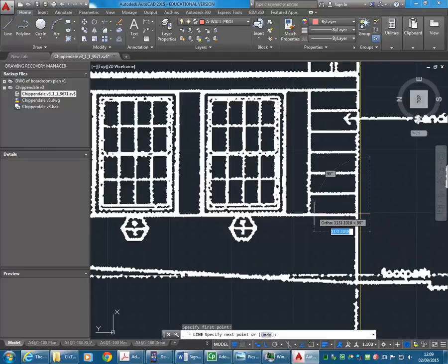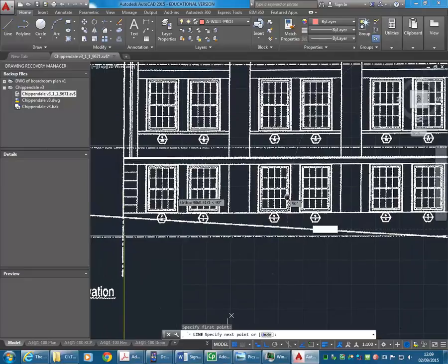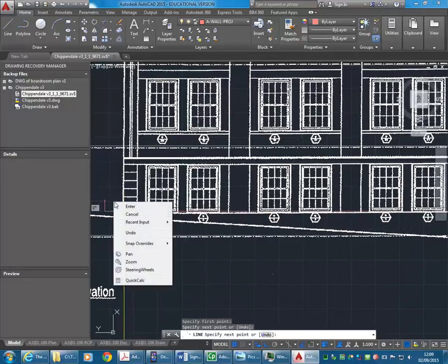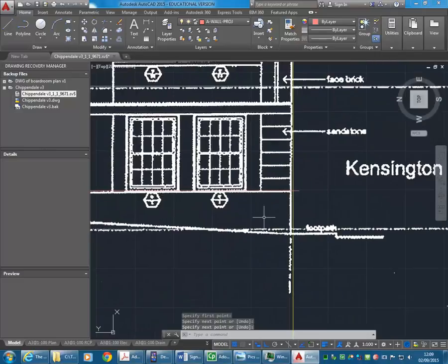Oh, there is. But it won't pick up the lines. Not these, no, and especially because they've been scanned in, it won't even snap to them. No, look, it's actually a bit of a secret in Revit that it can trace over pixel-based images. It's had programming in there for quite a while that will detect lines that are made of pixels.